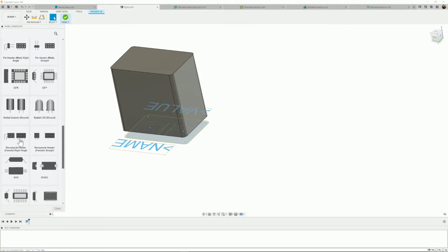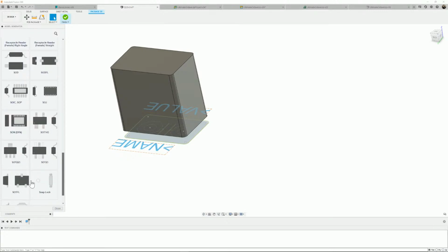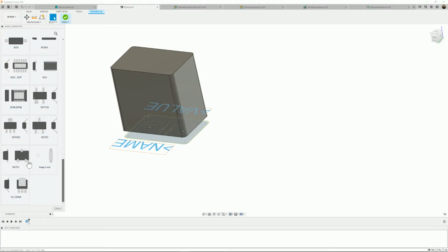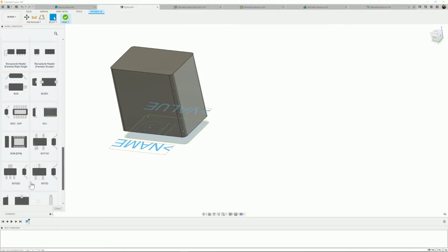It's super straightforward. It's just like any other IPC calculator. You put in the values from your data sheet and it builds. And maybe we can show one someday. It's not rocket science. It'll build the footprint accurately to least, maximum, nominal courtyard standard. And it will give you a native 3D body, not a STEP file, but a native 3D model that can have actual material properties assigned.